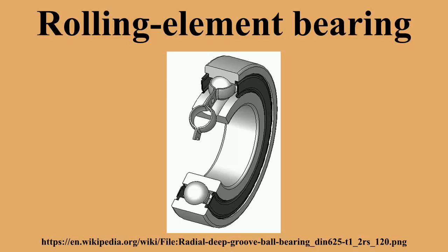For light loads, such as bicycles, ball bearings are often used. For heavy loads and where the loads can greatly change during cornering, such as cars and trucks, tapered rolling bearings are used. Linear motion roller element bearings are typically designed for either shaft or flat surfaces. Flat surface bearings often consist of rollers and are mounted in a cage, which is then placed between the two flat surfaces. A common example is drawer support hardware.